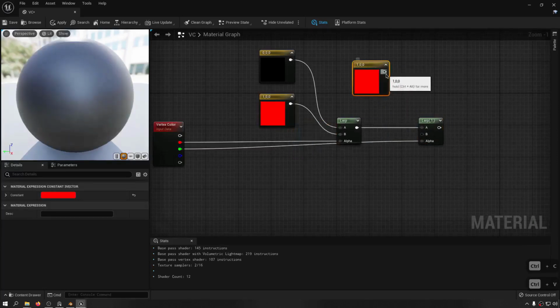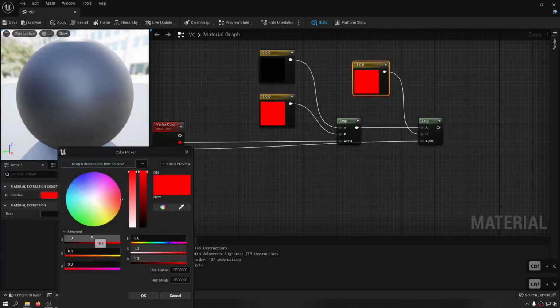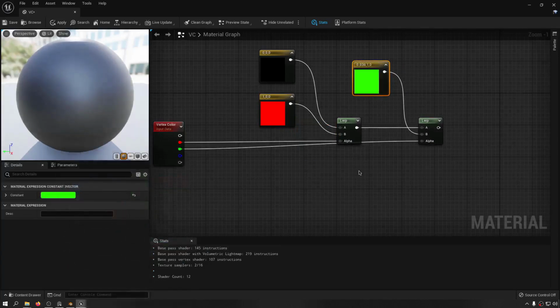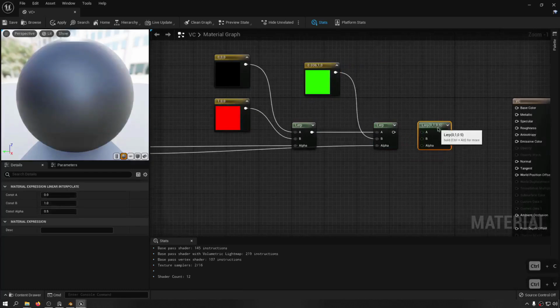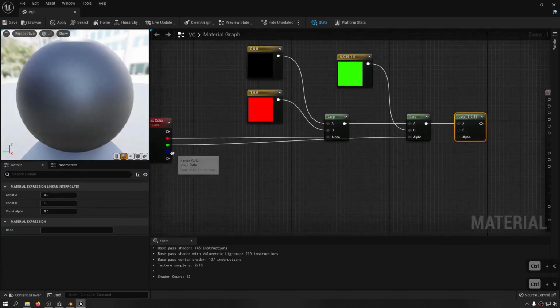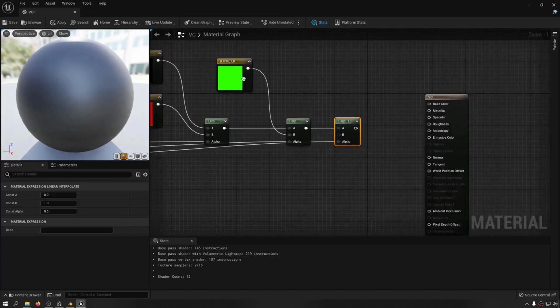And let's in here again assign this, and for visualization colors, let's drag the red down and bring the green up, and now it's going to use the green as a mask, and wherever it's green it's going to show B, and wherever it's not green it's going to show the previous ones, which uses this as an overlay effect. So again, let's copy this and bring the lerp into A, and now we're going to use blue. So we bring the blue into alpha, which is the mask.